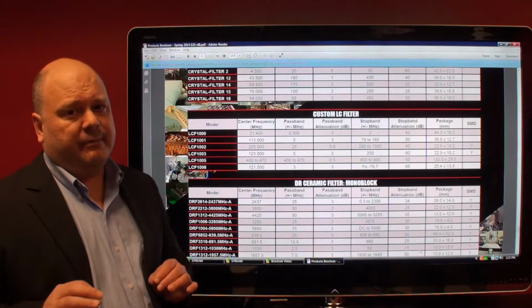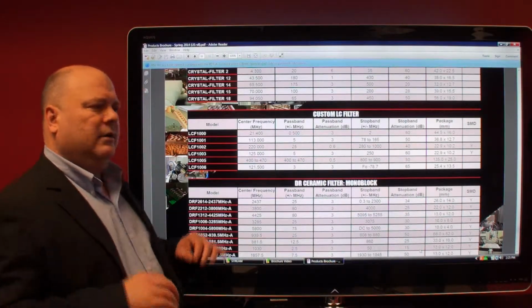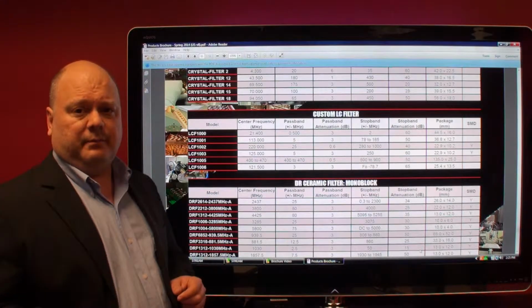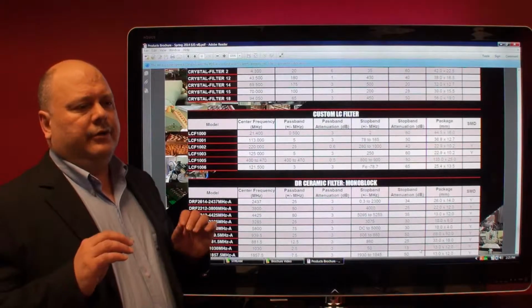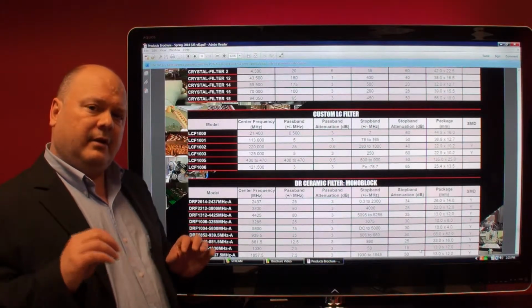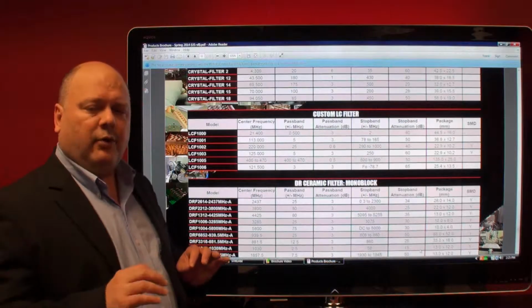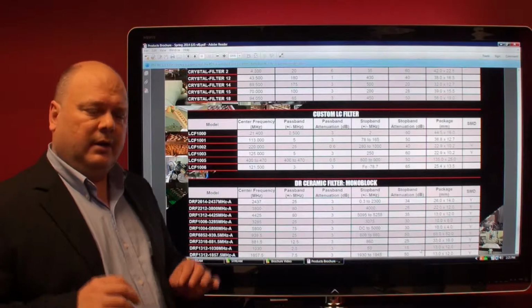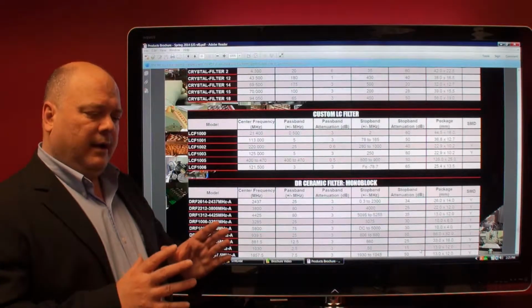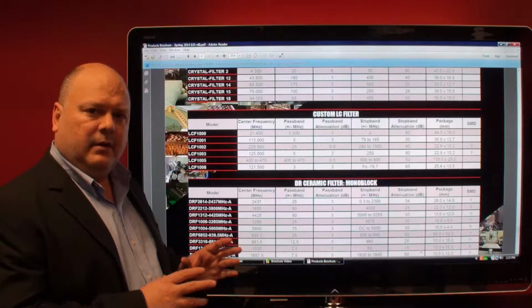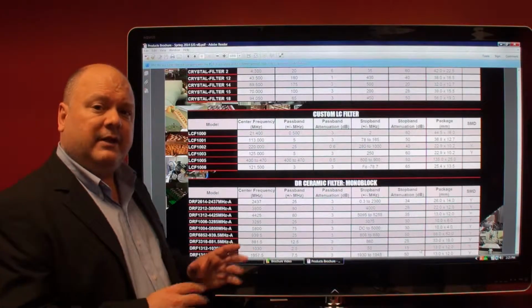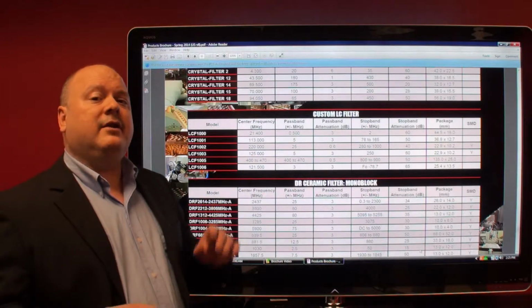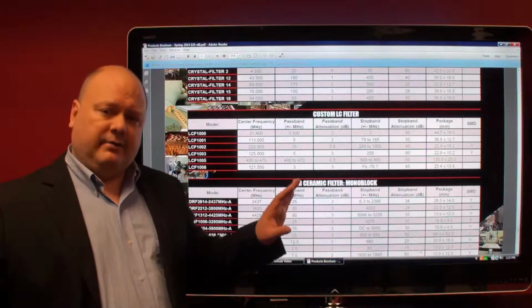Considering our RF system block diagram, I always go back to that. Always refer to your RF system block diagram just as a conversation piece with the customer. You'll notice that the RF filter, the filtering mechanism just before the carrier frequency is transmitted to the world, is near the power amplifier, and both of them work in conjunction to get the right output power for the transmit frequency with the right attenuation of out-of-band frequencies.